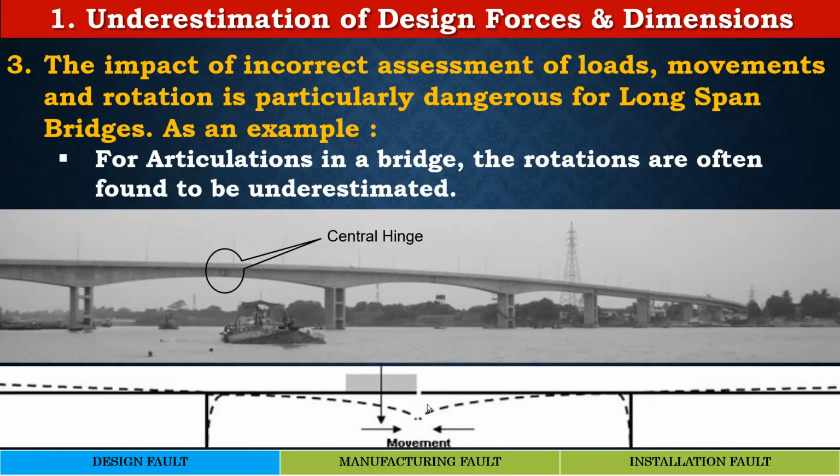And these rotations have to take into account not only the rotations caused by the live loads, but also the creep effect of the dead load, pre-stress, etc. And this calculation is quite complex. In many occasions, I found these calculations to be grossly in error, and the proper estimation increases the rotation by many fold. So I think it's very important that these are assessed properly.